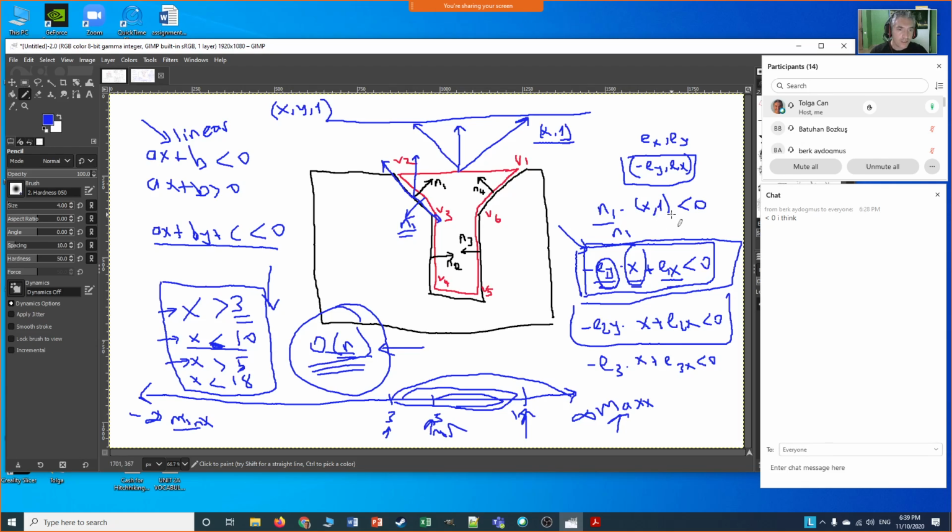Actually, you should have corrected me. If the angle is greater than 90 degrees, the pulling direction is bad, right? We want it greater than or equal to 0. So this is what we want for that pulling direction to be valid. But if this n1 is the reversed normal vector, in which it's the normal vector of the face of the polygon, then it will turn into something like this. So that's what we have in the book.